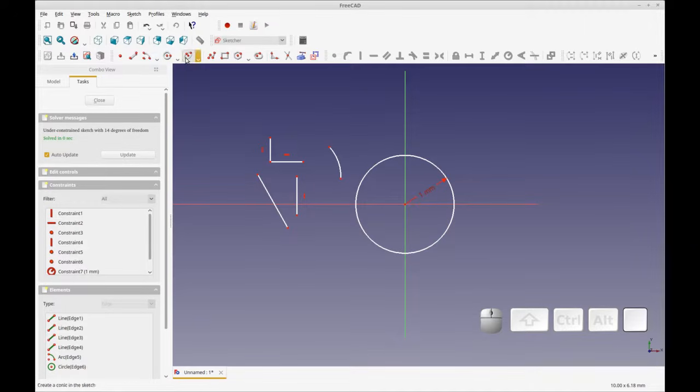Okay, so now an ellipse, much the same as a circle, but what the ellipse does is it uses construction geometry. This is a very useful piece. These are virtual pieces of whatever you're drawing, but they allow you to do more complex shapes and give them exact measurements. So now I can apply distance measurements to these construction things, and they affect my final shape.